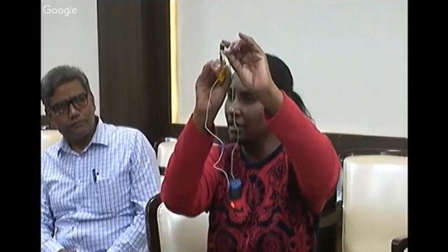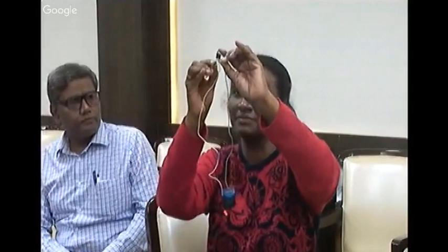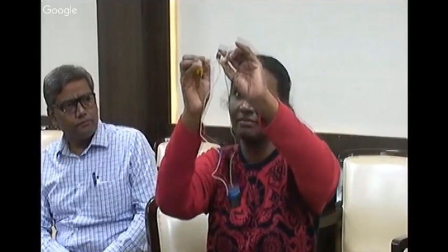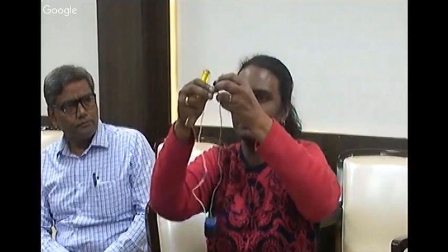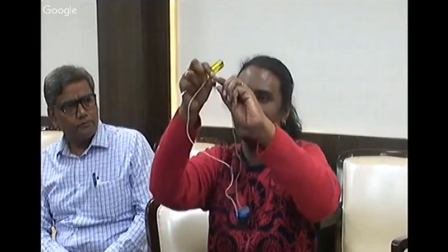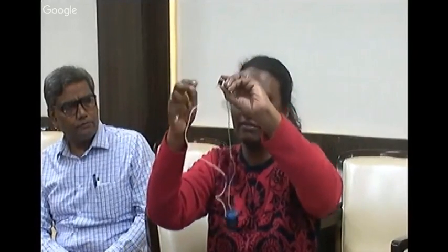So you can see my LED is glowing. Okay, I've connected. Now I'm giving the gate pulse to it. Now I'm removing the gate pulse. It's not properly connected, otherwise it will be latched. Oh, sorry, I just connected. When I turned it, it went wrong. My cathode is towards my left here. That's what I'm saying. Otherwise, it has to latch.